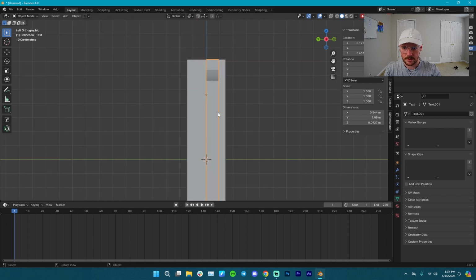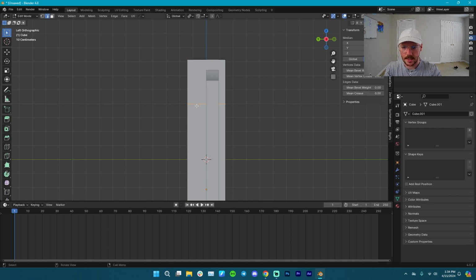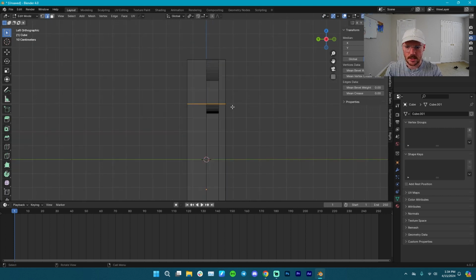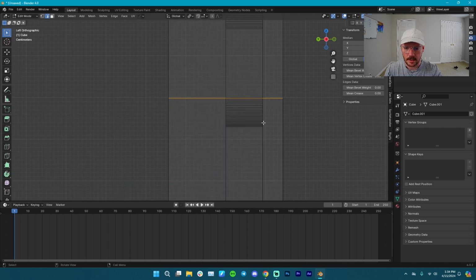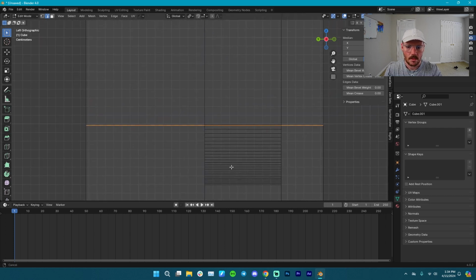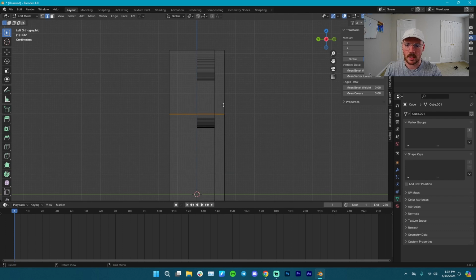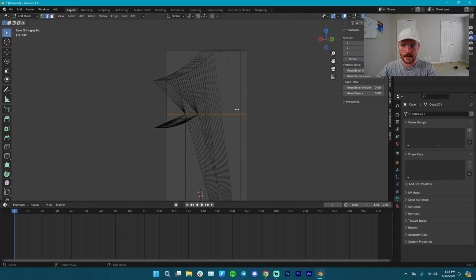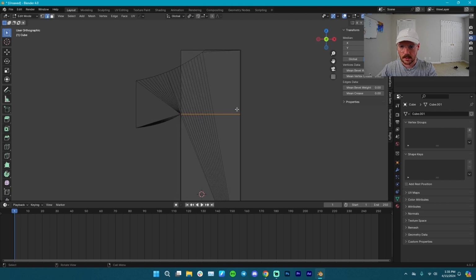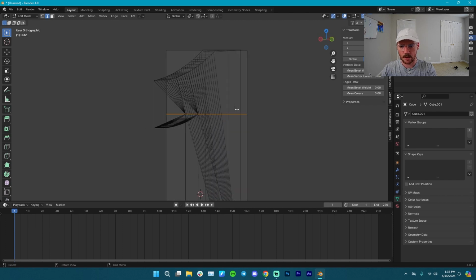Let's look at the left view. Click on my new box, hit edit again. And now I'm going to hit Shift Z. This is going to show me what I'm doing here. Shows a wireframe version. And if you have a number pad, you can hit 6 to look at things in orthographic, like 100%, zero perspective.